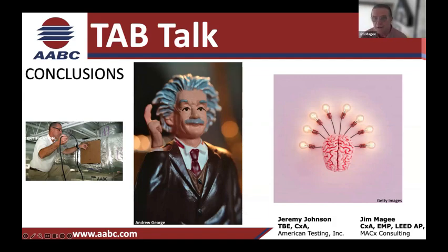it's the design authority who's going to really do the TAB verification. And really, my participation as a commissioning provider is going to be as much to make sure that things are fair to the TAB contractor as to the designer. For example, I don't want someone showing up with a piece of equipment that wasn't used to do the job. I want the same calibrated equipment that was used on the project. I'd prefer to have the same technicians there because they know where all the bodies were left, you know. So some of those things are really important, and I can help in that.